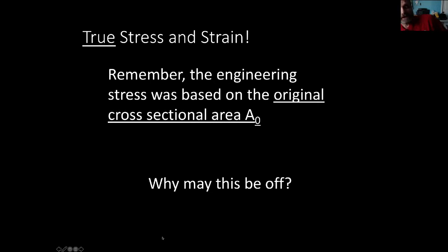So remember, the engineering stress was based on the original cross-sectional area A0. Well, this is not necessarily a perfect approximation of what's going on as you're stretching the material or as you're applying stress and resulting in strain in the material. The cross-sectional area will actually start to change as the material is being strained.